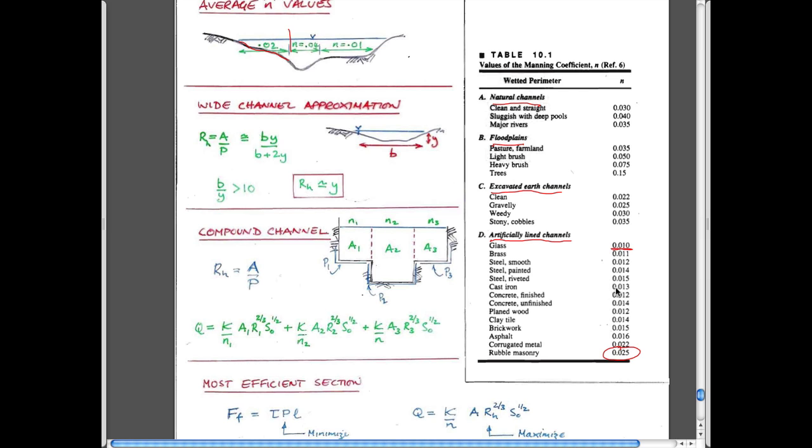They do not change with Reynolds number, so they just conform to the idea that we said before, that if you look at the Moody chart and friction factors, you have these different regimes. So we're always in this regime where we're turbulent, right? So they just become a constant number. They don't change. And I suppose for smoother pipes in the Moody charts, the magnitude of the friction factor is also small as well, right? I think. Can't remember.